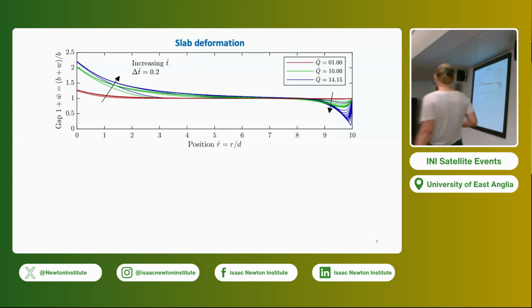So what's happening here? Basically, the reason why we're seeing that solution is because what introduces deformation in a solid is the pressure gradient in the liquid. So the pressure gradient that drives the viscous flow results in deformations in the solid, and most of the deformations of the solid are actually not vertical, they're mostly horizontal. It's the shearing of the solid.